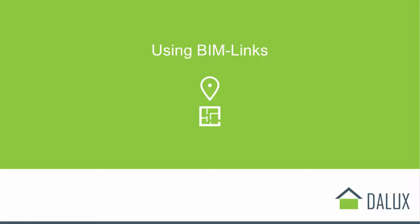BIM Links is an advanced feature on how to take advantage of good 3D models with uniform parameters and information to create BIM instances that can be used for creation or connection to assets. It's important to note that BIM Links has an effect on the entire Dalux FM system, so we have to have a uniform way of working with parameters and also be aware that once we upload new models in the future, they're also going to affect those.